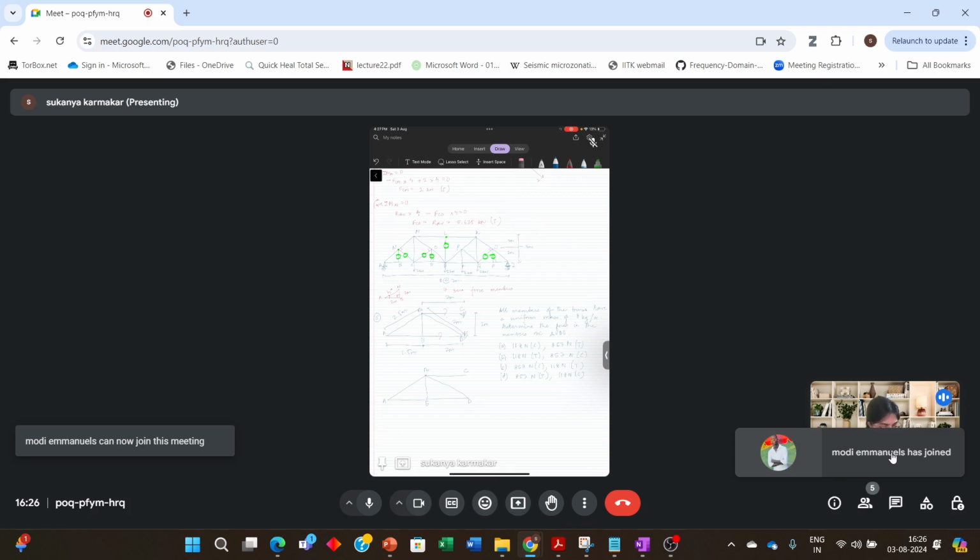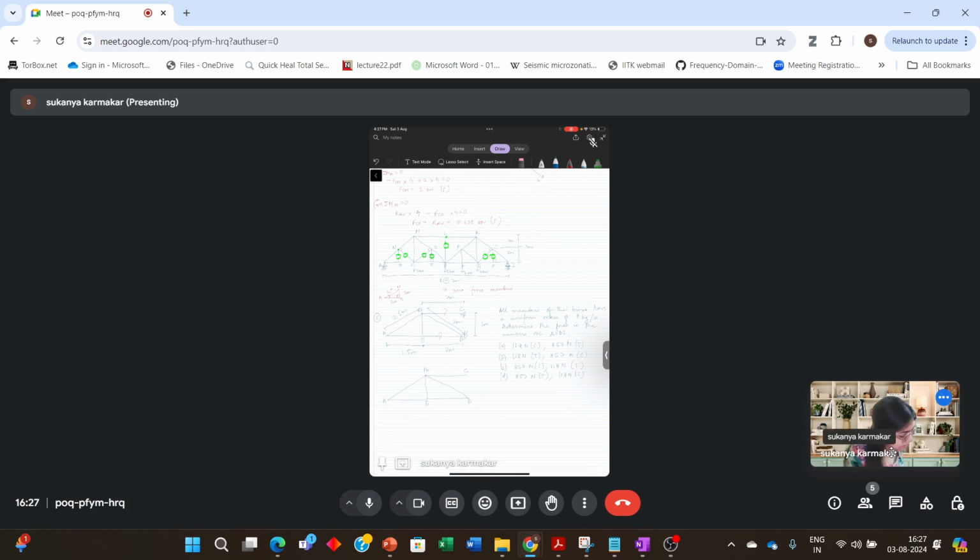So let's consider the member. Okay, I'm a bit confused in this question. Okay, let's consider the member BC. Length is 2 meter. So 8 into 2, 16 kg. Let's convert it into weight. So 9.81 times 16, 156 newtons, equally divided into 2 is 78.48 newton. So here and here it will be lumped equally.